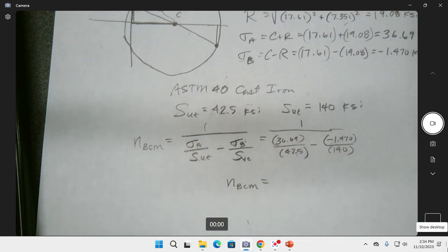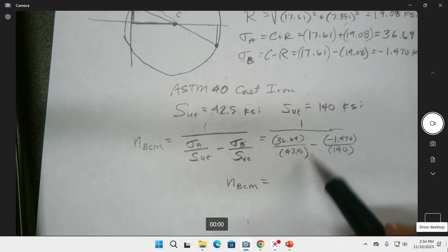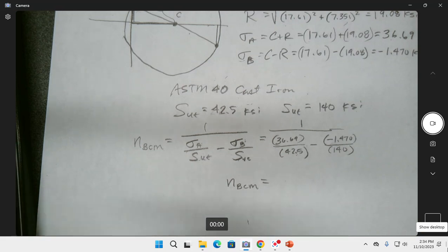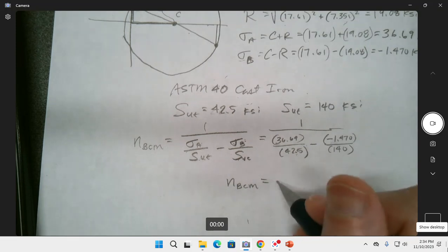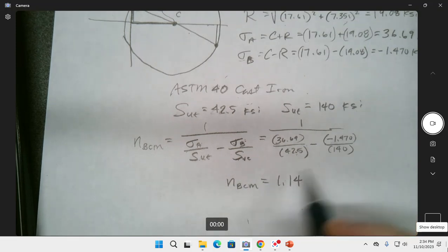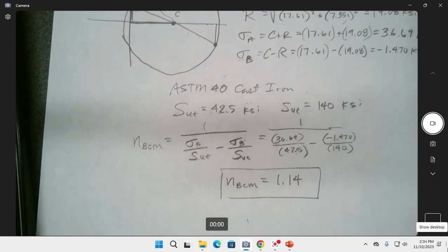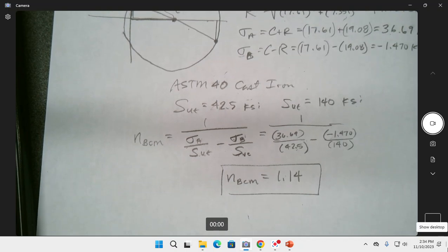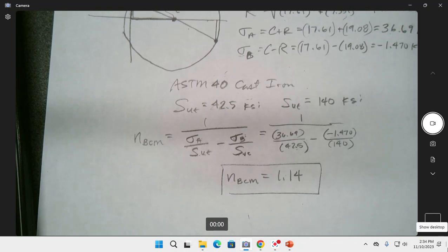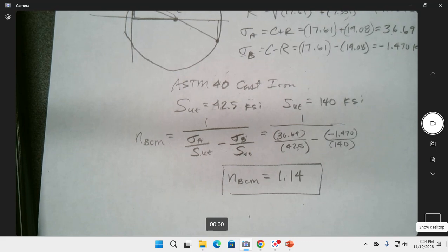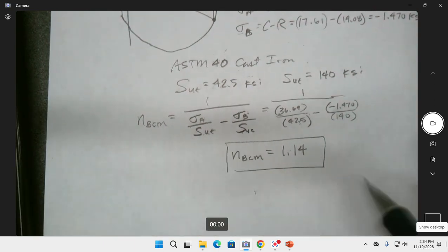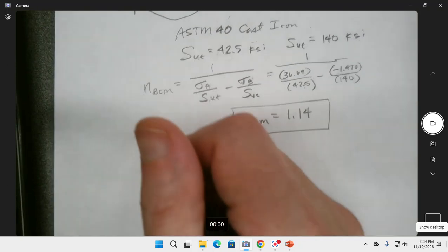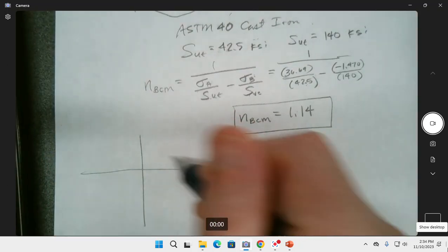And then you add the two things together. So you've used up, on the denominator here, 87.4% of the capacity. And then you take the inverse of it, and you get 1.14 right there as being your safety factor. It's a different way of thinking of this, with it in the denominator. What is safety factor? Sort of the inverse of how much of the capacity you used up, the percent of it that you did.